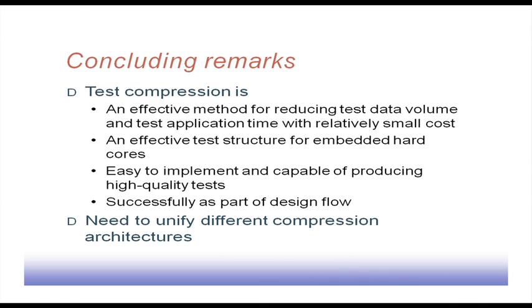In conclusion, test compression is an effective method for reducing test data volume and test application time at relatively small cost, because we don't need more advanced ATE to store a huge amount of test data or apply the test at a higher frequency.